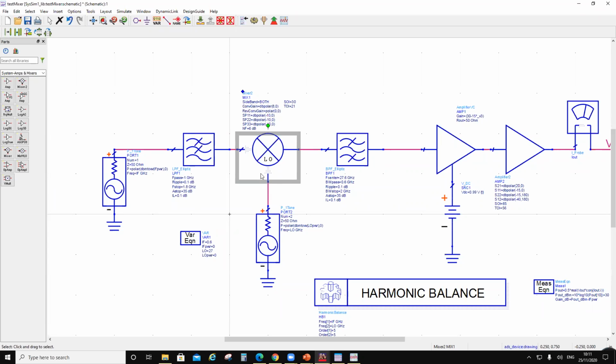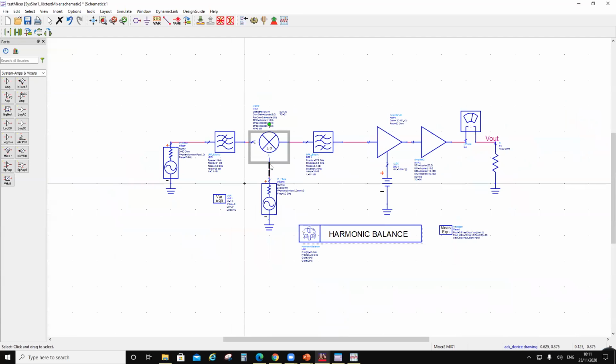Old guys used to put attenuation pads everywhere, and then they would minimize leakage components using attenuation pads. Now if you design the mixer to be well balanced, then even harmonics are not an issue. It's odd harmonics which are the issue. So as a designer, you should take this into consideration. So this is all the input I'm going to give you on this one.